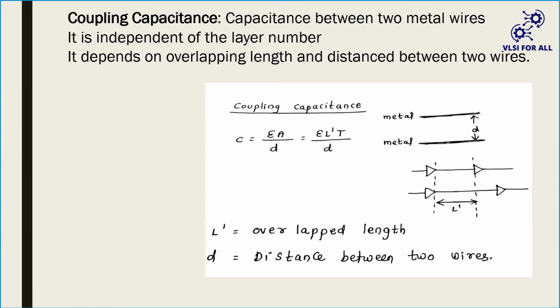And you can ask me how the delay is interrelated with the capacitance. Yes, team, each and every tool vendor follows their own strategy. They don't reveal it to the public domain, as per their security guidelines. But what I want to convey to you is, if there is a metal wire or net, how can you calculate the delay for that? There is a standard procedure called Elmore delay.